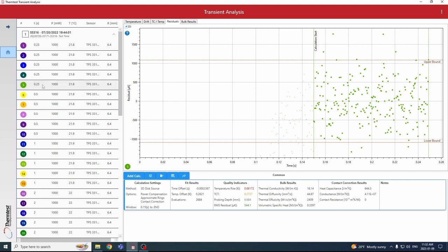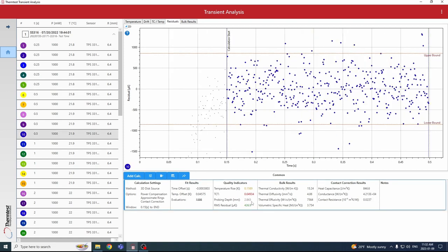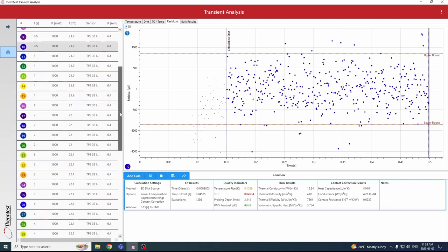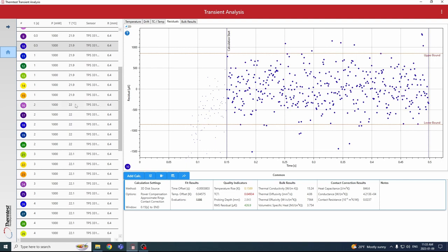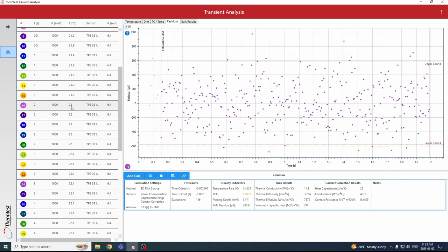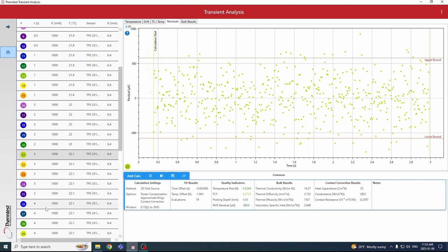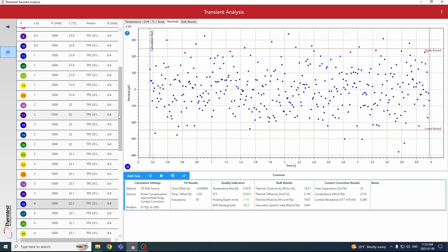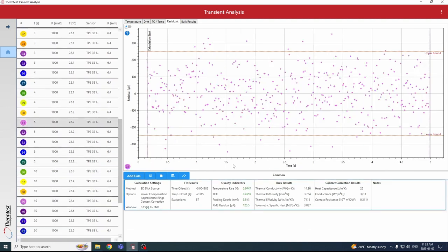So as we look at the data from these various test times on the stainless steel sample, you can see we have a large range of penetration depth available. So 0.5 seconds, we have lots of penetration depth available. So we want to select a test time that approaches that minimum, so that we're getting a representative volume of sample included in the measurement. There's 2 seconds, 5.4 millimeters, 3 seconds, 6.68, 4 seconds, 7.7, and 5 seconds, 8.6. So we have lots of range.